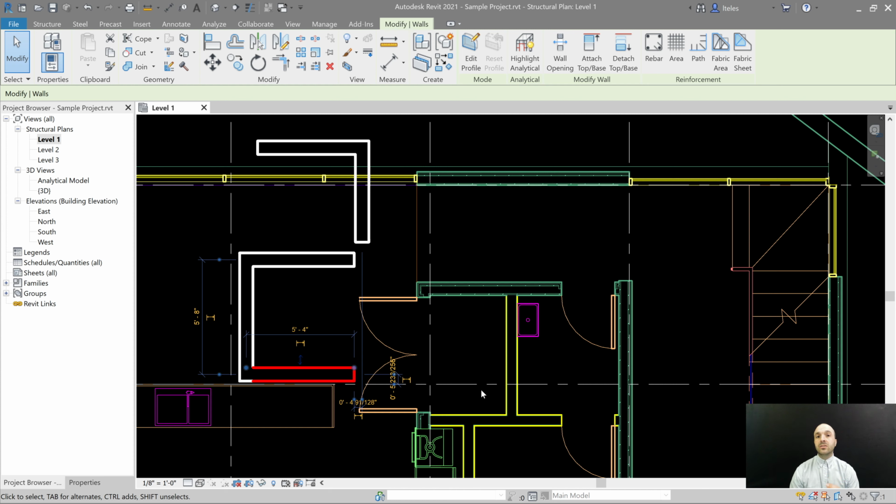When the location lines are correct on your walls, it becomes so much easier to make changes to that wall later down the life cycle of the project. Because it's very rare that we're going to model a couple of these walls. It's very rare that that wall will stay exactly where it is until it gets built. The thickness of the wall might change, the material might change, a lot of things might change. So it's important now, as you're setting up the beginning stages of your model, to take all of these settings very, very literally. It will come organically the more you do it.